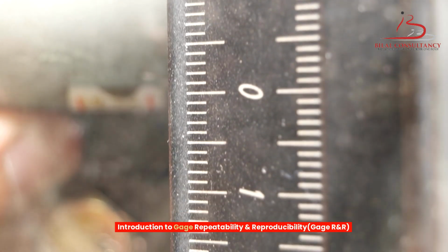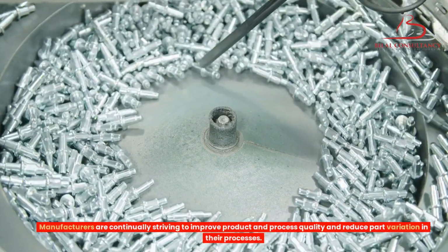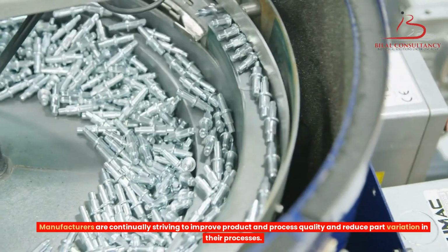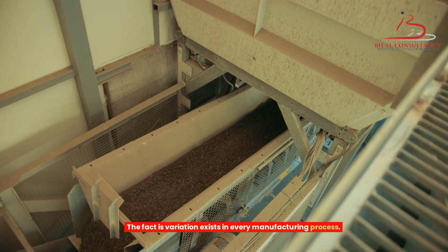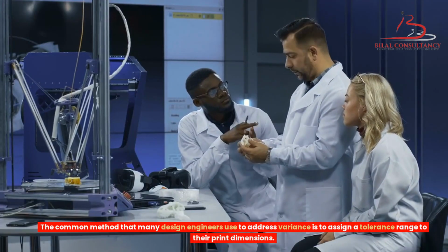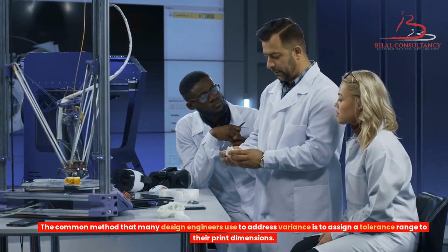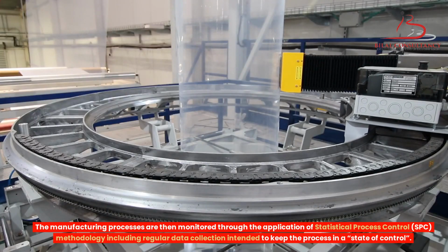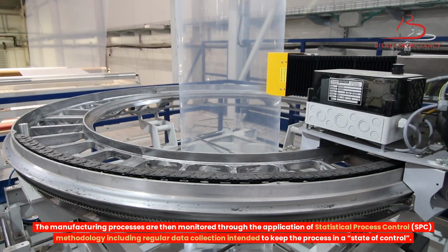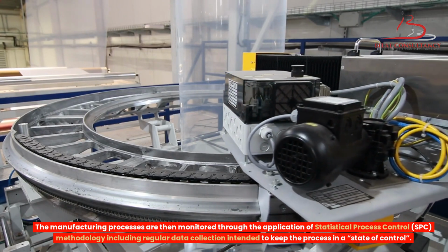Introduction to gauge repeatability and reproducibility, GageRnR. Manufacturers are continually striving to improve product and process quality and reduce part variation in their processes. The fact is, variation exists in every manufacturing process. The common method that many design engineers use to address variance is to assign a tolerance range to their print dimensions. The manufacturing processes are then monitored through the application of statistical process control (SPC) methodology, including regular data collection intended to keep the process in a state of control.